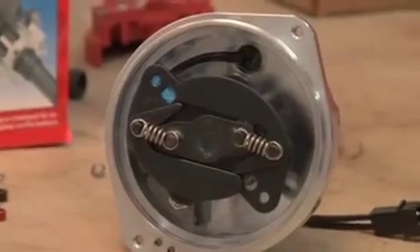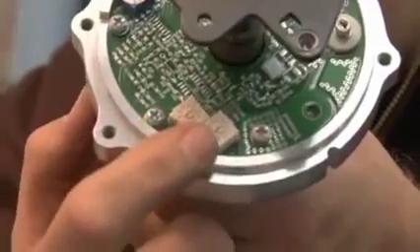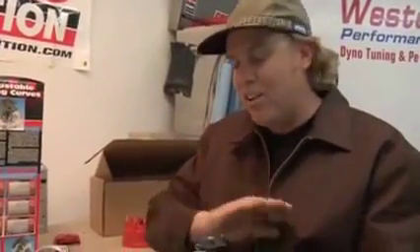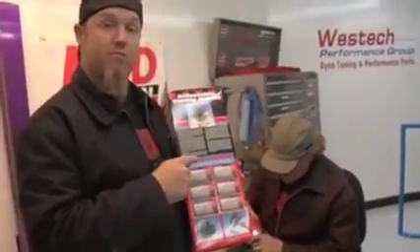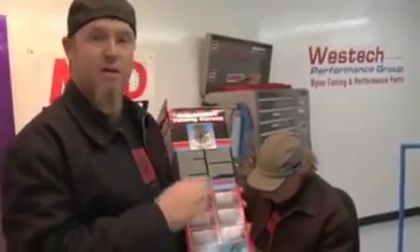It's pretty easy to change those springs on that Pro Billet distributor, but you can make it even easier on yourself and not have to deal with any centrifugal advance mechanism if you pick up one of those MSD digital E-curve distributors, at which point all you have to do is change a couple of switches here with a little tiny screwdriver, and you can set your entire ignition curve electronically. Don't forget that all the information you need is right here on the side of your distributor box. It tells you what springs and what bushings will give you what combination of rate and total timing sweep.